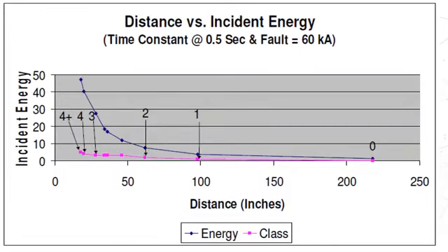There you will find a number of questions in the exam related to this concept of working distance and scope change. Just keep in mind that the risk assessment is performed for a particular working distance. That's why, in the incident energy analysis method, I showed you there is a working distance given, and in the PPE category table method, the PPE is selected based on the working distance. So if the working distance is not followed, all your risk assessment will be null and void. Any question on this concept?